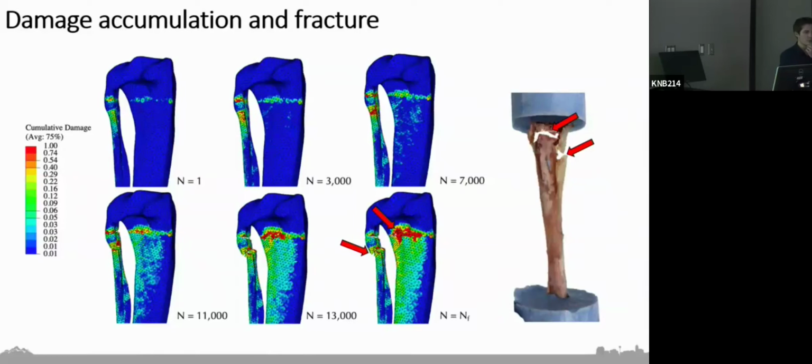When it comes to cortical bone, the stiffness of cortical bone is roughly linear with respect to density. When you get to trabecular bone, it's roughly quadratic with density. It has to do with something called cellular solid theory, how trabecular bone fails by buckling. And buckling stiffness has a power in there. So when you do the optimization, you get some B value that's, I don't know, somewhere between 1 and 2. Yeah, 1 and 3. 1 and 3, okay.